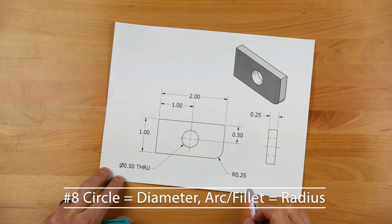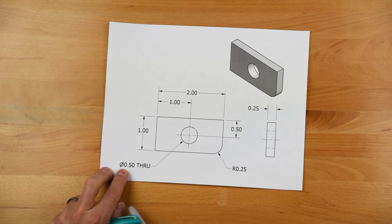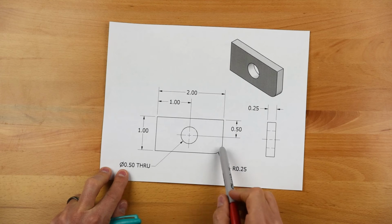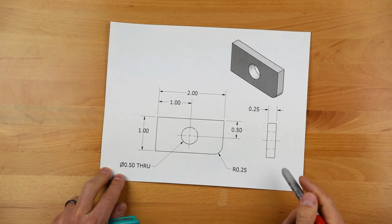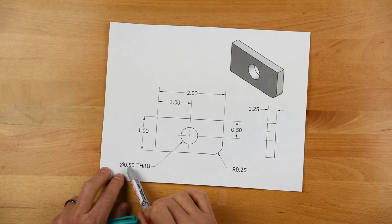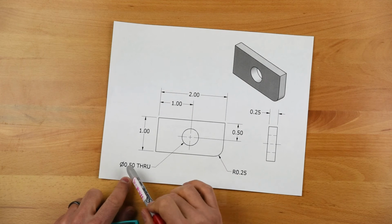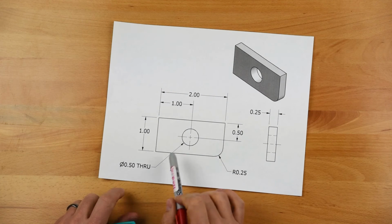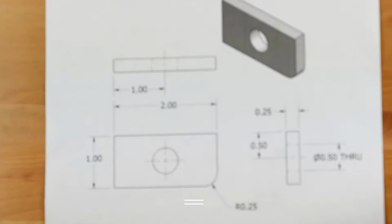Here's just a general idea, is that when we have a circle, we're going to dimension our circle with the diameters, and if we have fillets, we're going to use radius. And so in this particular example, again, it's just to make sure that when we have this circle, don't be using radius. Sometimes that can happen based on the software package that you're using. We want to make sure we get that changed over to diameter when dealing with circles. Fillets, okay, radius.